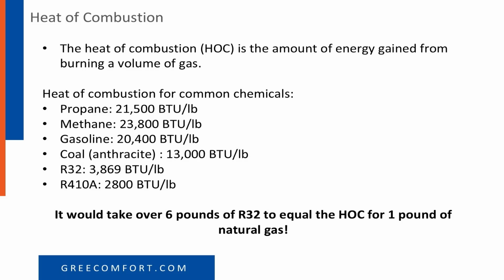And again, just to put a pin on it there, R410A, I talked about it burning under the right conditions. Even it will produce 2,800 BTUs per pound. So again, with our A1s and A2Ls, they're releasing very, very little heat compared to the hydrocarbons. And why that's important is because if you do have a flame with an A2L refrigerant, it's going to be very low heat. If you want to burn something like plastics and other things, typically you need much higher heat to set those on fire, melt them, things like that.